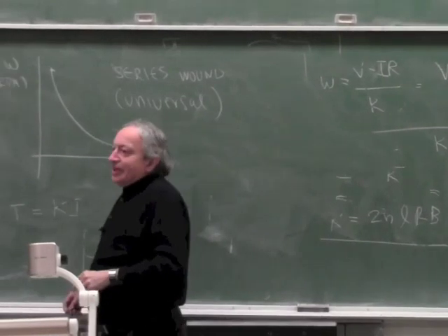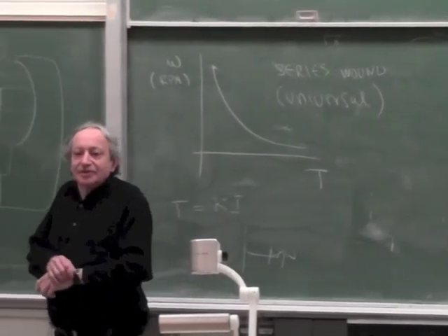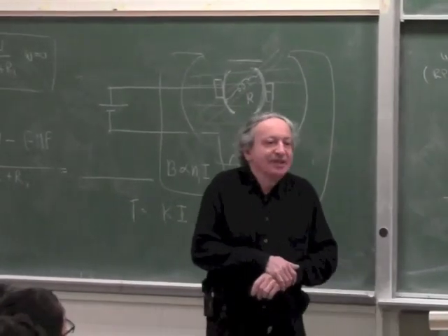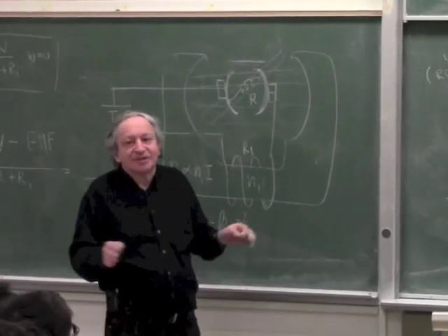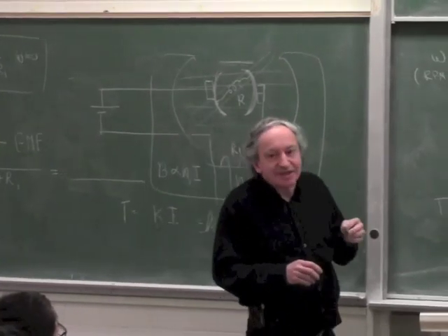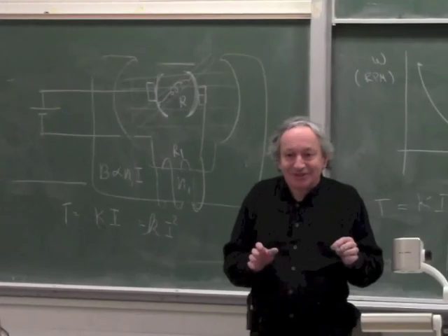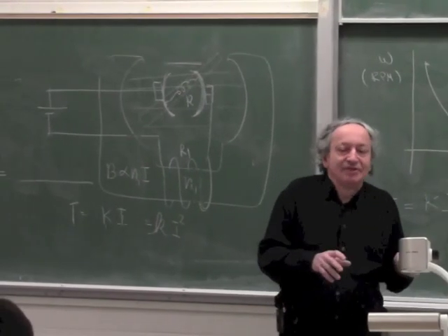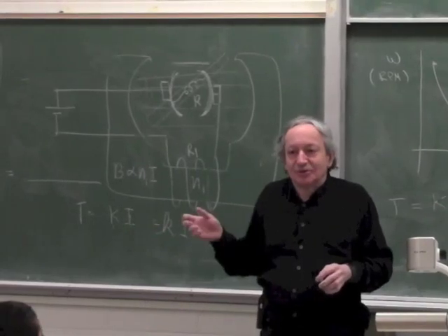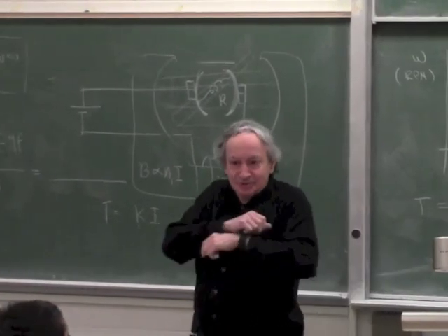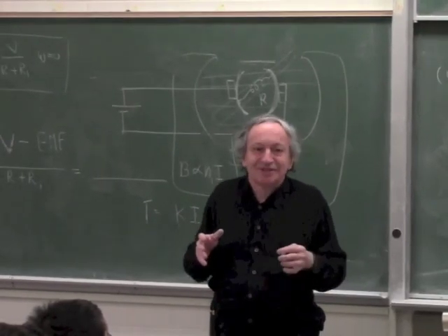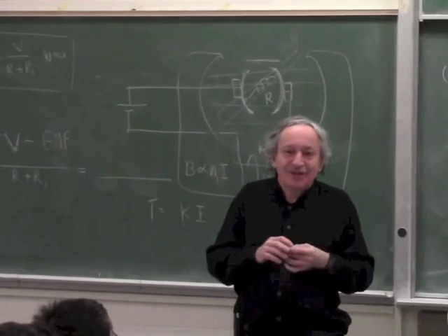Sorry, so is it the air resistance that stops the transmission? Yes. The only thing which stops a series wound motor from exploding is the air resistance. And actually, these motors can run at dangerously high speeds. Because if the motor was designed to drive some load, and you just turn on a big motor without the load, it will explode to pieces. Because in a big motor, the motor has a lot of torque, and the air resistance is not so big. So you have to be very careful with these motors.